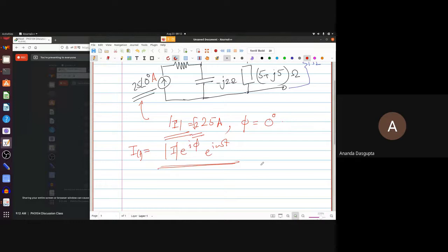If somebody says the current is 10 sine omega t, something like that, as in another problem, there you are actually specifying the current I of t, and you can easily see that this 10 is not the RMS value, it is actually the amplitude. The RMS value actually is 10 by root 2, if you wanted the RMS value in that problem. In that problem, you did not need the RMS value.